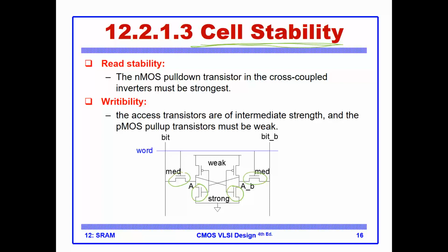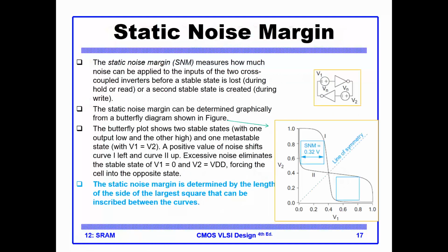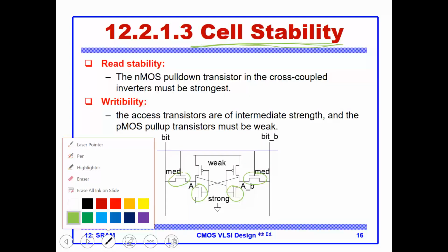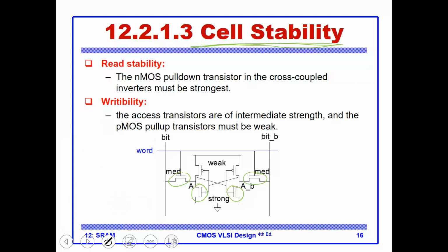Okay, that's for sure. And then what we said, it is important for the write operation that the access transistors are more powerful than the P transistors.